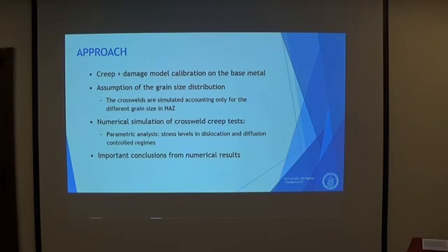Here I summarize the approach. Basically, we have a constitutive framework for creep deformation accumulation and creep damage. We have calibrated the entire model for the P91 steel, and the most important thing is that the calibration is made just on the base metal.